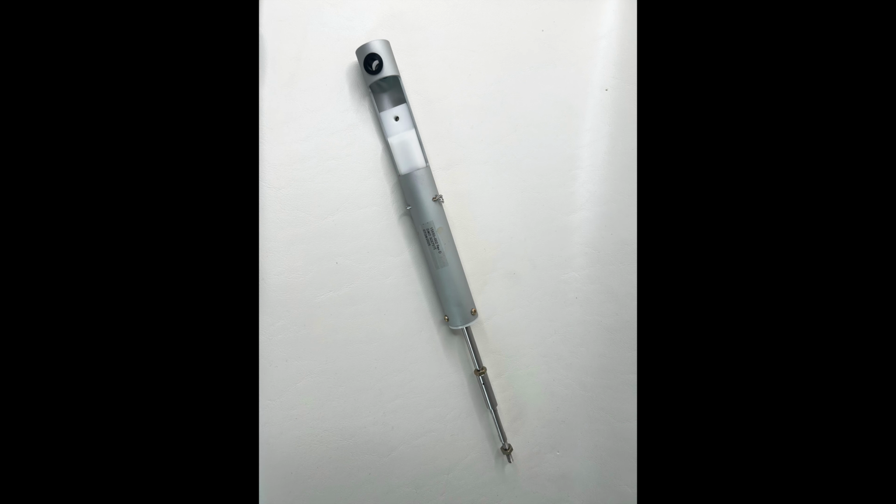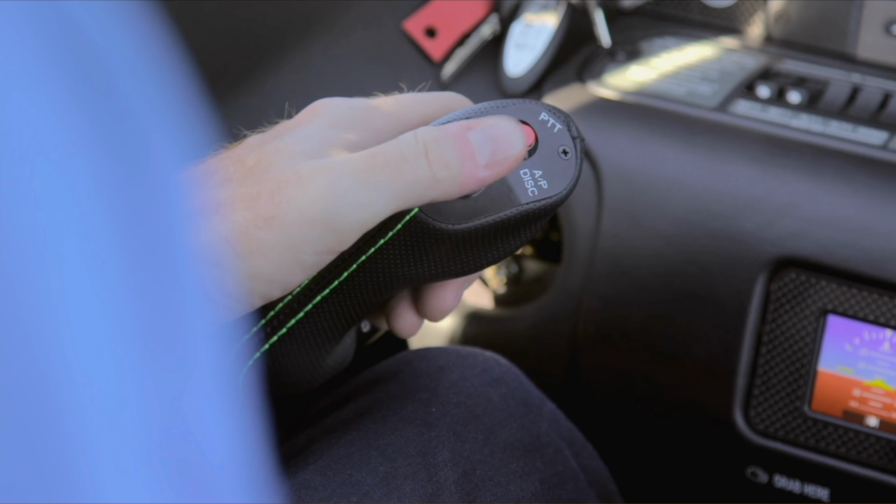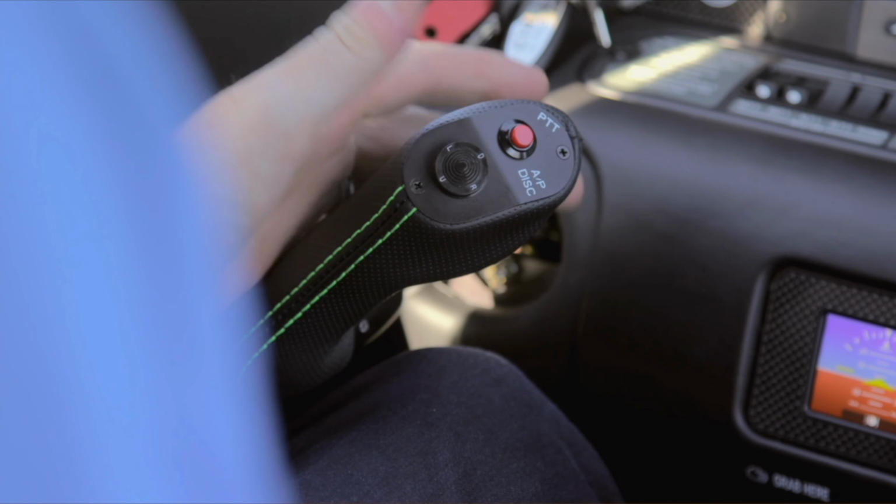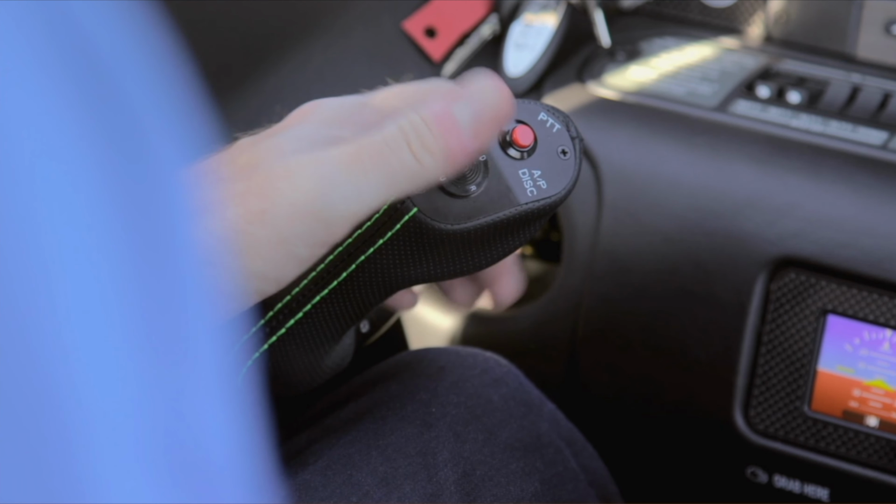But that's not the only way to do this. For example, a Cirrus SR-20 doesn't use a trim tab at all. Instead, it uses a spring cartridge in the control system. A switch on the side yoke drives an electric motor that changes the spring preload, which changes how hard the controls push back in your hand. The hardware details can vary. The underlying idea does not. Trim creates a steady force so your hand doesn't have to.